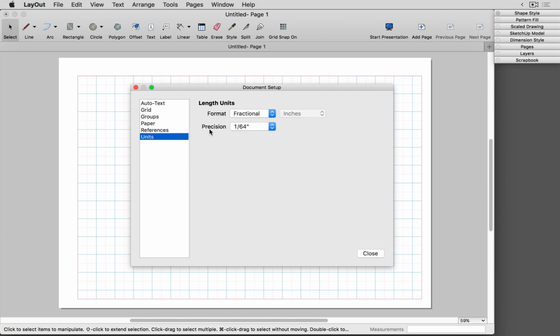Lastly are the settings for controlling our drawing units. For this lesson, we're going to be using fractional units. Feel free to keep as decimal if you like. Just note that with fractional, we'll be adding inches and feet to our measurements and dimensions later when drawing and annotating.